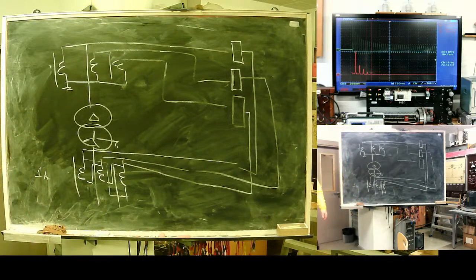Usually a large power transformer comes with a set of current transformers. They are sitting where these huge insulators are going out. Below them, there are cylinder-like attachments. Inside will be a set of current transformers, 3, sometimes even 5, flat current transformers.